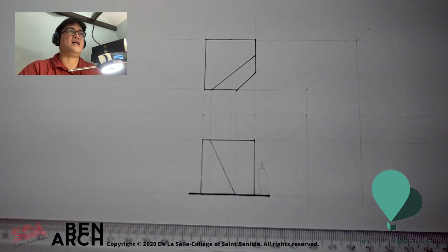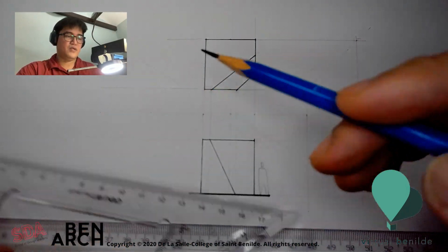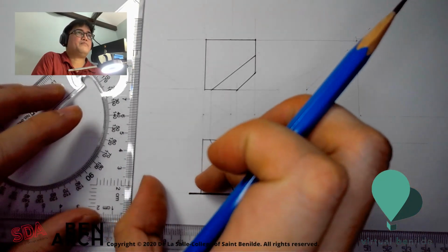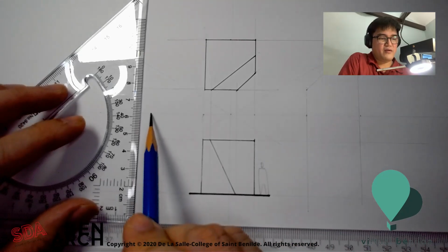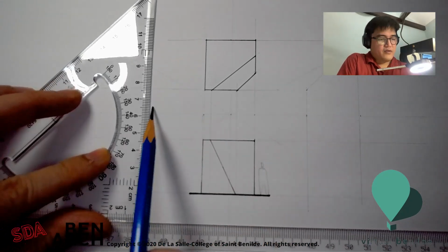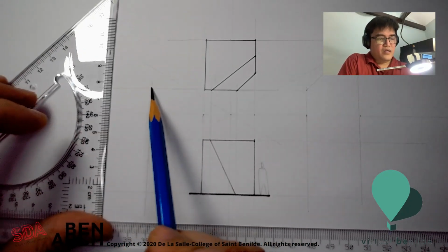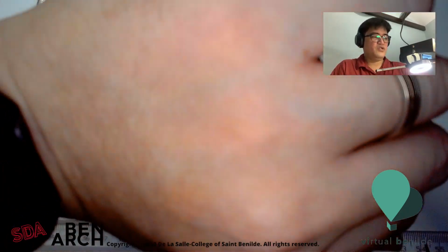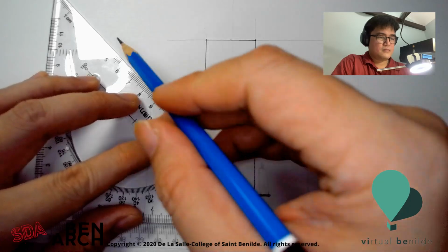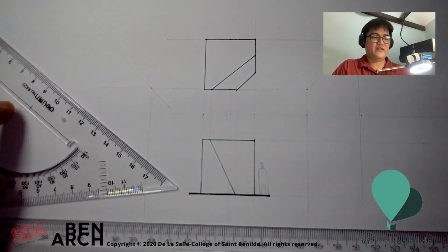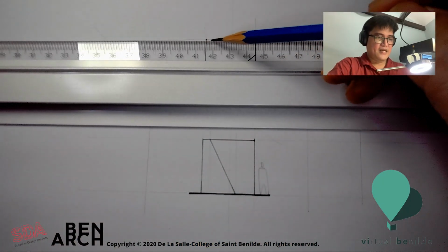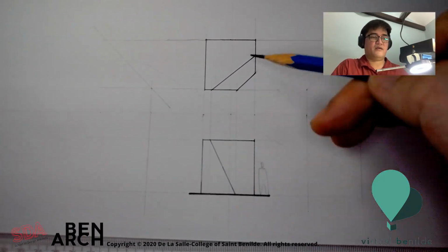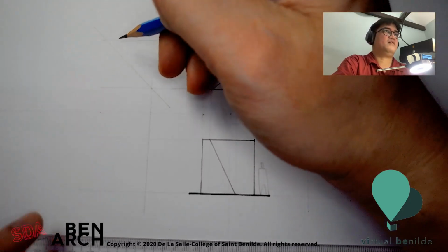Here we have that. Then we need to do the same. Again, there's this 3-meter gap. The 3-meter gap is somewhere there. We already made a point there. Create a vertical line, only meeting up to here. Use my 45-degree triangle. Make a 45-degree. Extend this line, which is aligned to the edge of your top view, until it meets that corner.